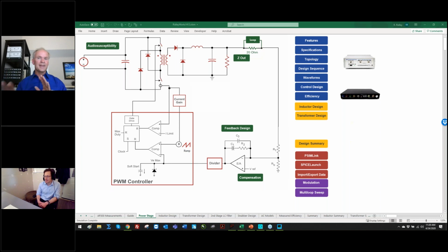So getting the LT Spice and Psim populated with a working converter is a huge, huge step in your design process. Don't underestimate how much that can change your design life. You shouldn't be worried about convergence and what kind of switches and doing this and doing this. You shouldn't be spending a week getting your converter to run. You should be spending 3 minutes to get it to run. And then you're designing. You're actively putting in those extra circuits that you need. And that's fun. That's the fun part. Fixing convergence is not fun. No.